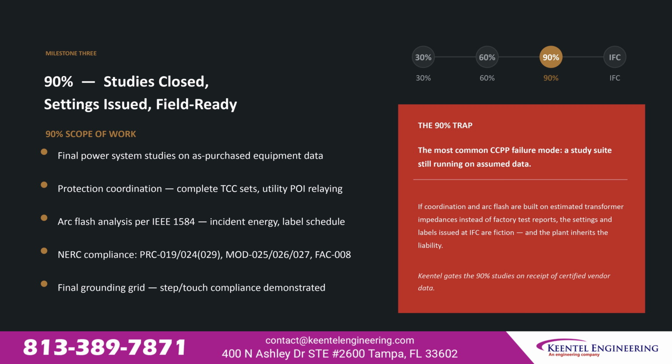The 90% trap is the most common CCPP failure mode: studies still running on assumed data when the milestone is declared. If coordination and arc flash are built on estimated impedances rather than factory test reports, the settings and labels issued at IFC are not valid, and the plant inherits the liability.